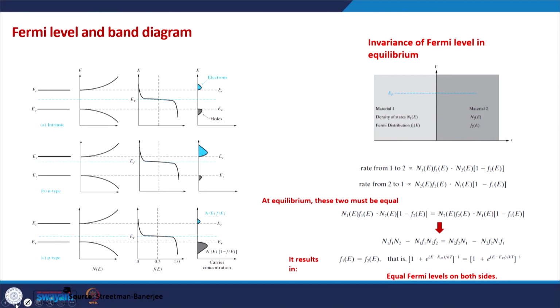So after the density of states, we tried to understand the Fermi level, the idea of Fermi level, Fermi distribution function, because in a device, generally the channel region is extremely small. So we need to understand the density of states of the channel. The contacts are bulk. We need to understand the Fermi distribution functions, the Fermi levels of the contacts.